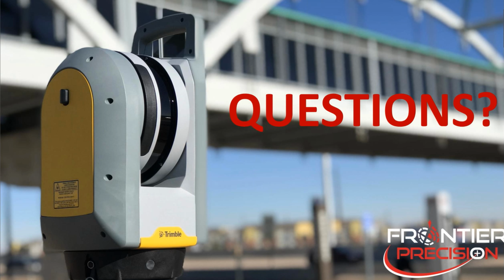In terms of the flight and the data collection, Nathan, with the YellowScan or the LiDAR, I don't think there's really anything too special you have to know. If you can fly a drone, you can pretty much fly the YellowScan. It's just basic mission planning and some manual calibration maneuvers, right? Yeah, you're exactly right. The mission planning's a little bit different, and there's some manual procedures to initialize that IMU. But other than that, you're still mission planning and letting the drone do the flying for you. Right, so the operation of the drones is pretty much consistent.